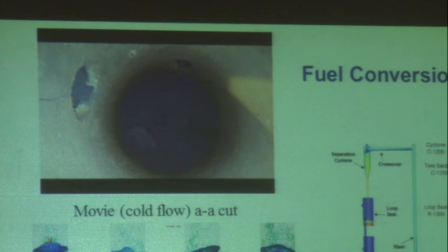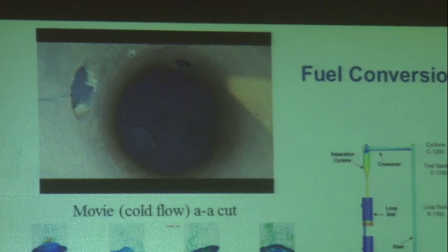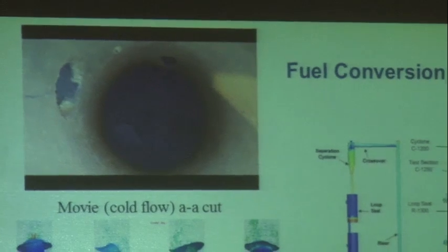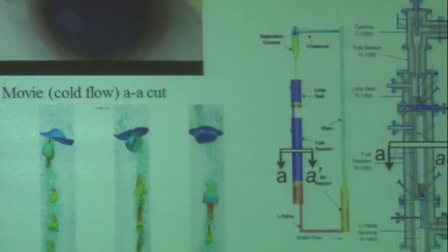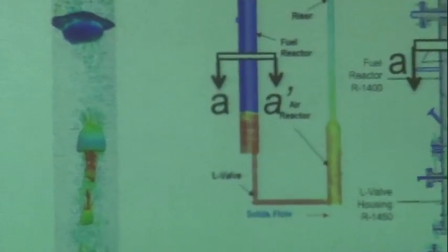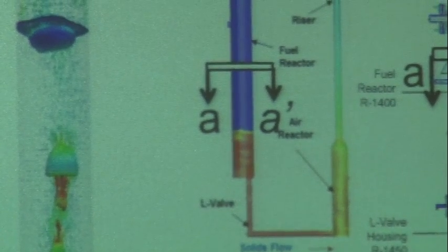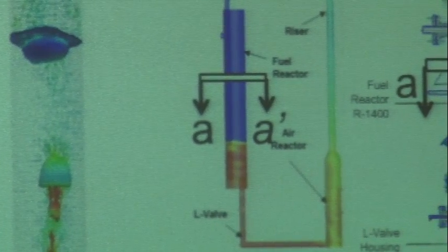Well, this was actually a test on natural gas. If you put coal in there, you'd have the solid reactions. The coal you could keep in the bed, but you can't keep the gas in the bed, right? You pyrolyze the coal or you gasify the coal, it's going to go into those bubbles, all right? So this is the tricky part then. As those bubbles leave the region where they would contact the metal oxide, what happens to them? There's no oxygen in that region. Nothing happens to them. They go out the exhaust where you don't want them.